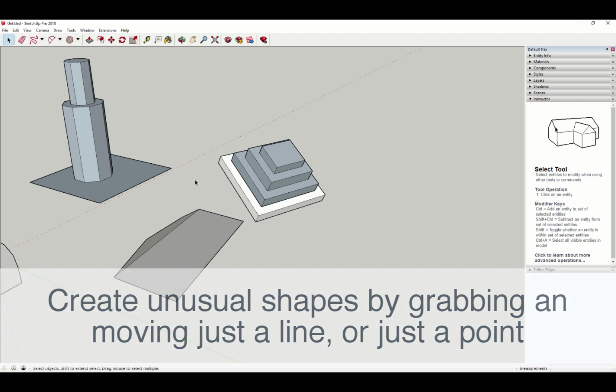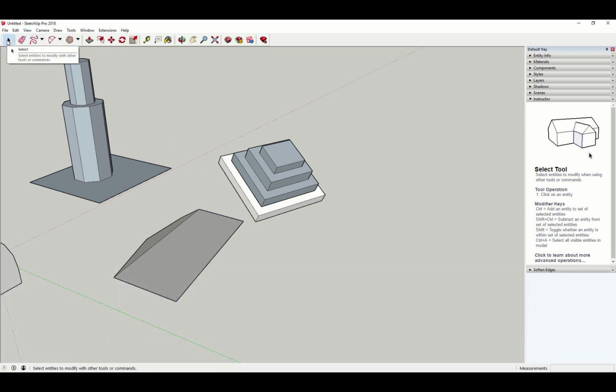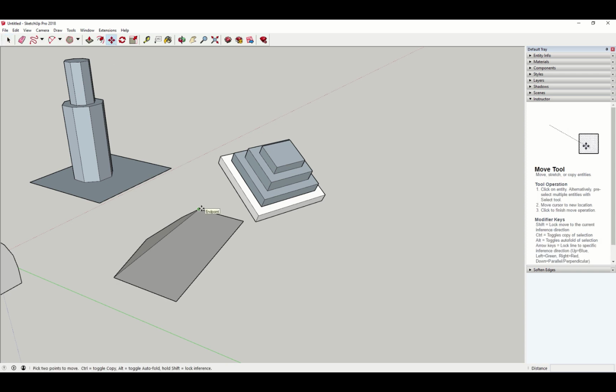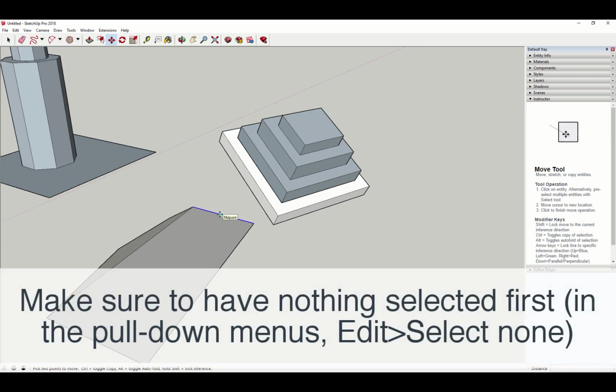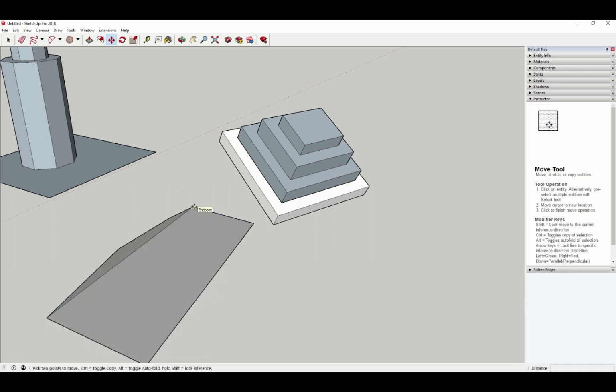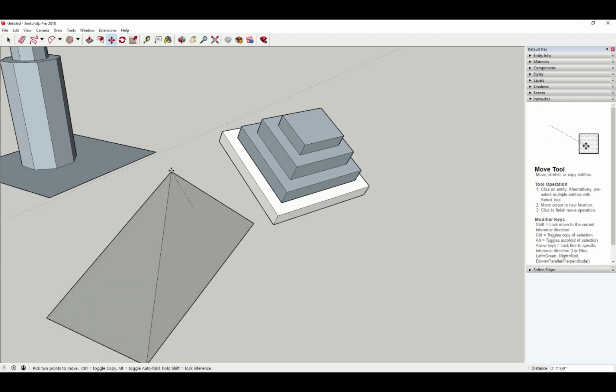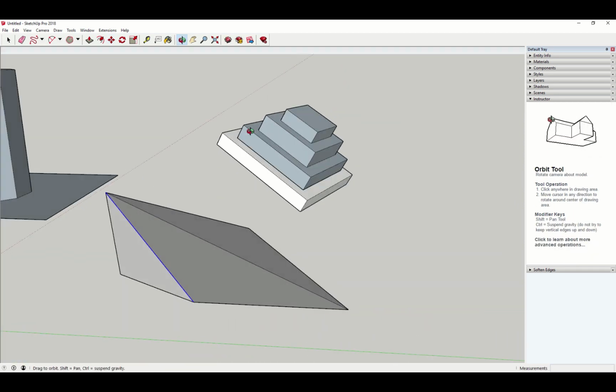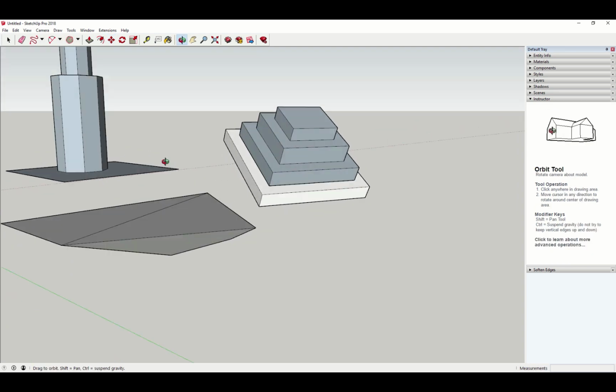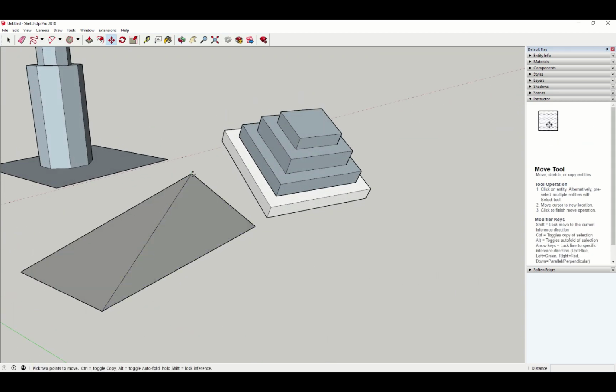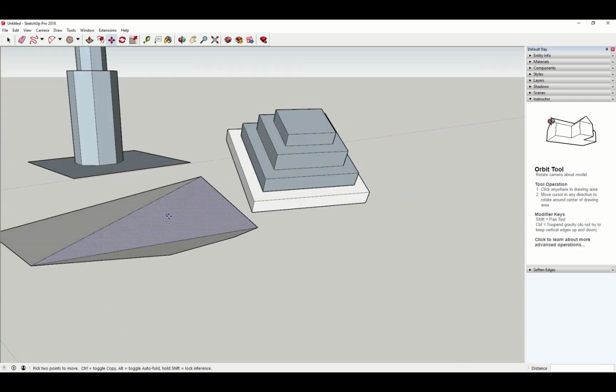In fact, if I have nothing selected, so I'll click the select command, click out in outer space, so nothing is selected. When I hit the Move command, I can let SketchUp automatically select the objects. You see how it highlights them, either the surface, the line, or this endpoint. I can move endpoints either up, down, left, or right. Again, SketchUp will try to modify the geometry so that it automatically warps to make whatever shape you want.